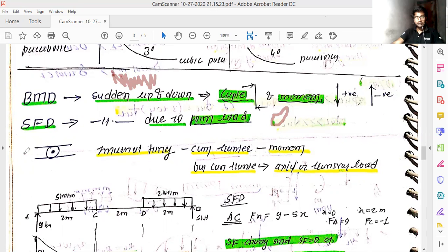Now we move to another section, which is the internal hinge. An internal hinge is one kind of connection between two links, like two links connected by a nut and bolt kind of cross section. In this condition, no moment is going to be transferred through that link, as there is no moment present in the nut and bolt kind of cross section. Once it is fixed, it will be fixed, but it can transfer shear load as well as axial load. Mostly they ask questions on this. If you know the concept behind the hinge, just keep in mind there is no moment transfer.